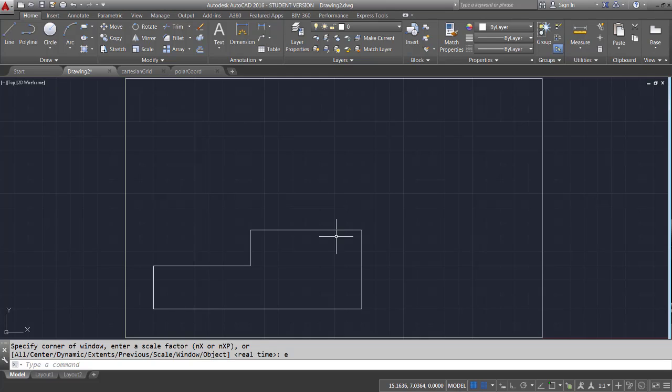Okay, so we've done a little drawing here using the ortho mode and using the snap mode on the screen with the snap increment set. And we've drawn a couple of basic, essentially rectilinear objects. And we've done some zooming around with the zoom command so we can see our objects. All right, I want to get rid of these objects so we can get into some of the other drawing aids and see how they may help us in drawing maybe some more complex objects and drawing something other than at 90 degrees.